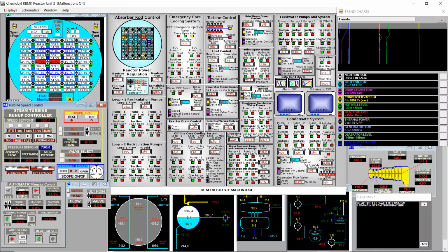And when I press enter, you will see the generated load increasing a lot, because we have now some excess pressure that we can turn into energy. So 33 megawatts. Now we are far enough from zero. I think we can safely switch into main valve, and we see main valve opening while startup closing, generated load increasing to 80 megawatts or so. Okay, so everything looks fine.